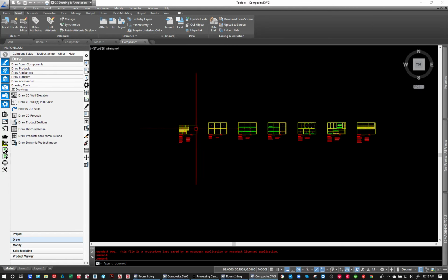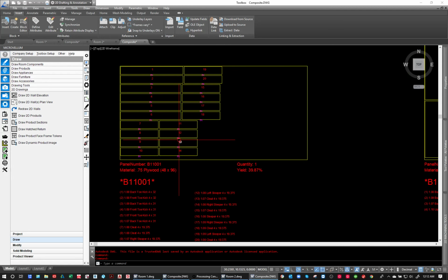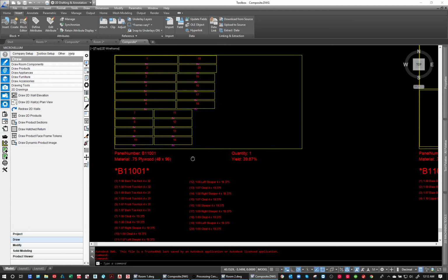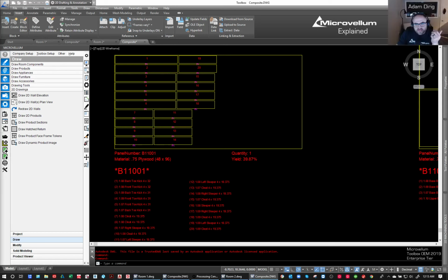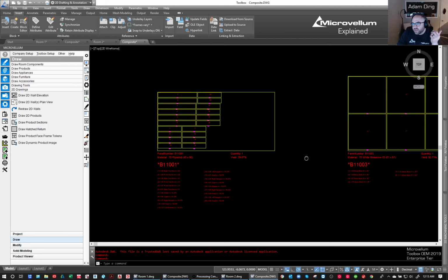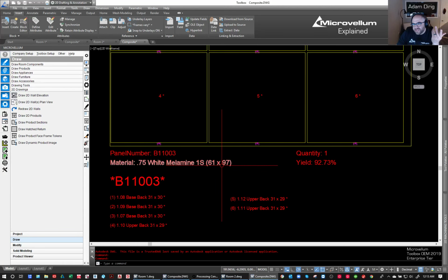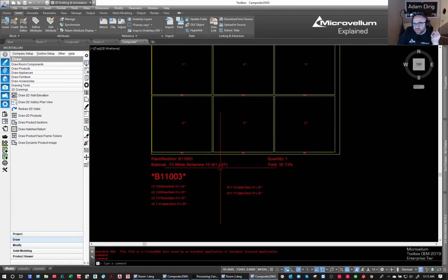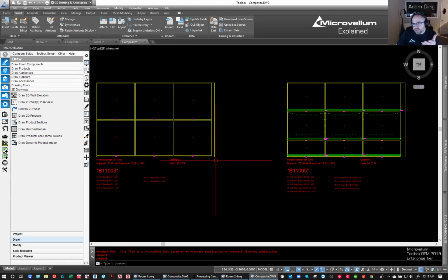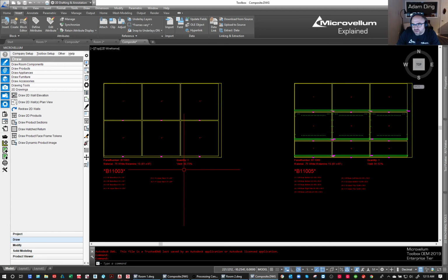This composite view has got everything laid out. So this is our 3/4 inch plywood for the kicks. I have a separate kick for each base. And this is telling us some yield. My melamine's set for 5x8, which is a sucky yield. I mean, it's actually pretty good yield in this situation, but generally I like 5x9 material. But see, here's my yield there.